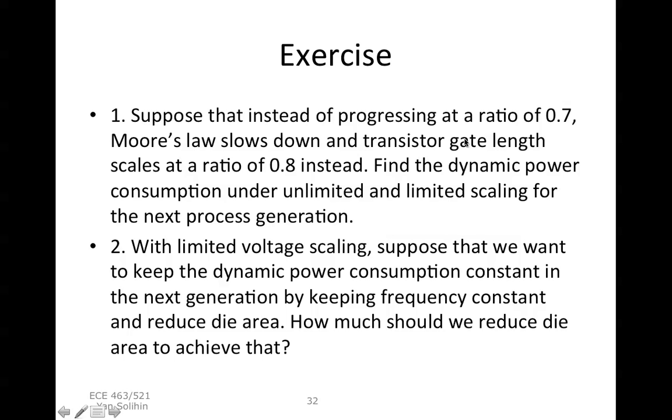So let me conclude this module essentially by saying that the switch from single core to multi-core is caused by, and is extremely related to, the power wall problem. Essentially, the fact that we cannot reduce threshold voltage as we enter a new process generation.